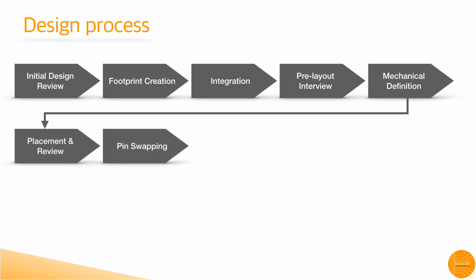Step 7 is pin swapping. For routing convenience sometimes it's necessary to do pin swapping. Before doing it, be sure to consult the datasheet of the part and verify the pinouts and ensure it is capable or not.